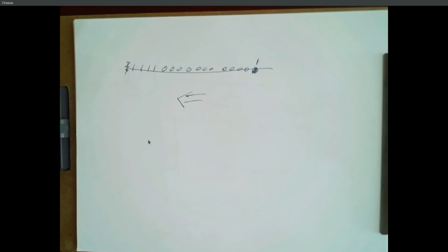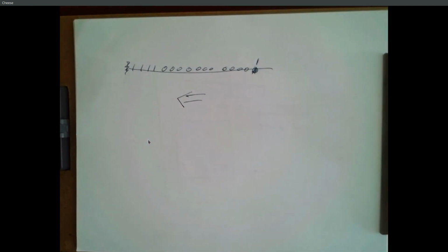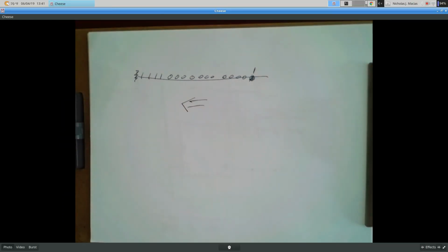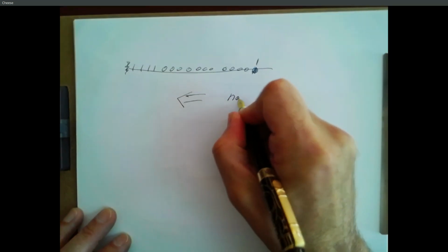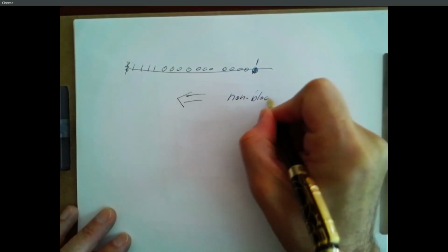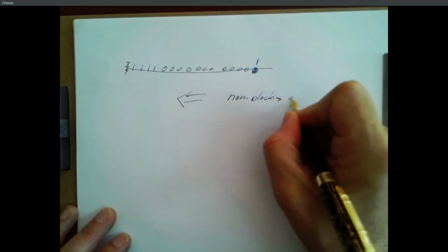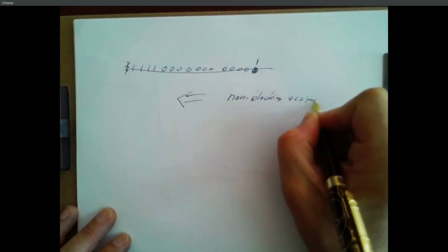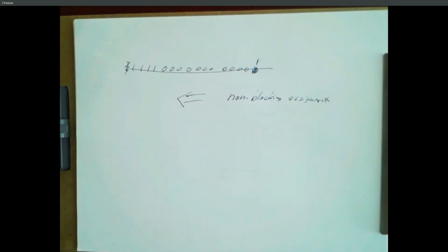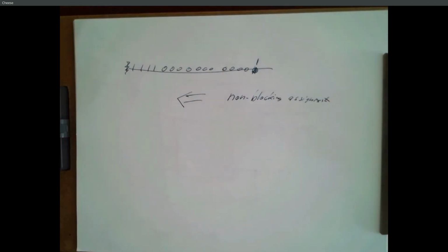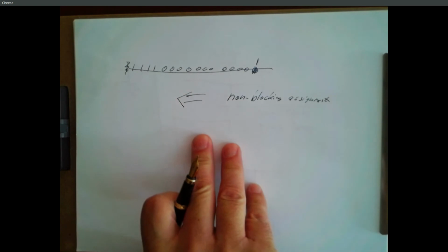So let's talk about this thing. I've said inside always blocks, you should always use this symbol. This is called a non-blocking assignment. Non-blocking means it happens more or less instantaneously, and it doesn't stop other things in your Verilog program from happening.